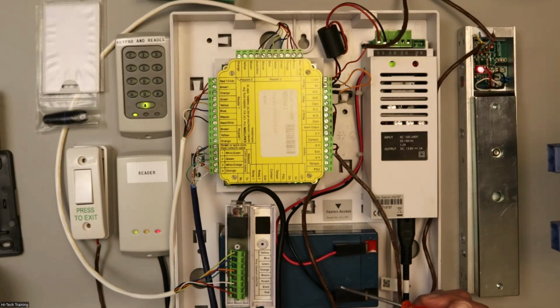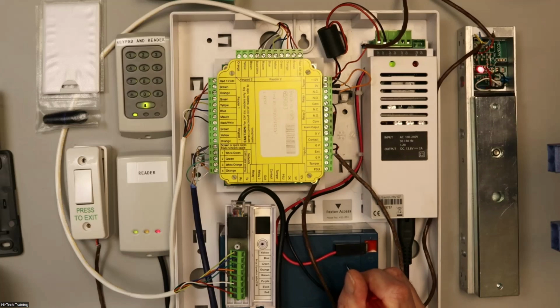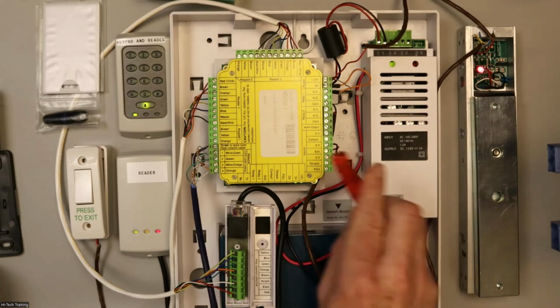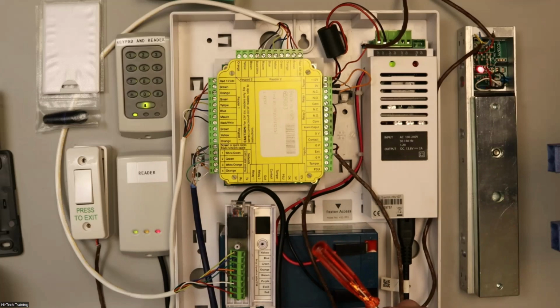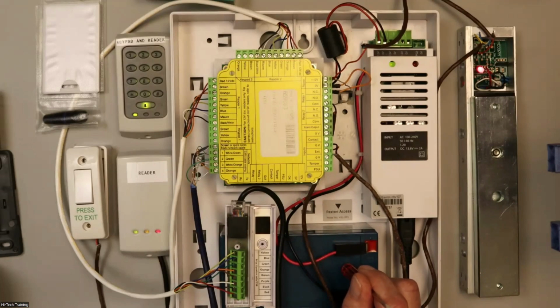Put a battery on here as well for backup power, but I've just picked a 4 amp hour battery there. The size of this battery is determined by your Maglock and all the various items you've connected on, and how long you want the battery to back up the system for. Just because I've got this size battery here does not mean that's the correct one. We have a separate lesson included in our course on choosing the particular battery size. It's a big deal about batteries.